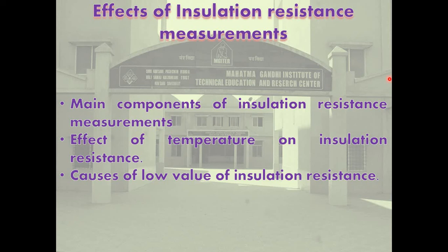The carbon particles, metallic dust, and sludge have a tendency to align along the direction of the electrical field on the internal and external surfaces of insulators in the presence of moisture.